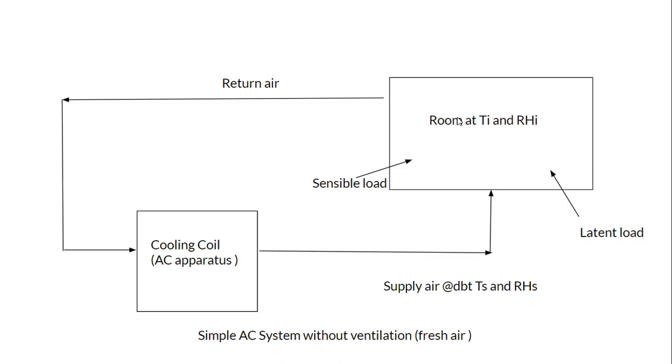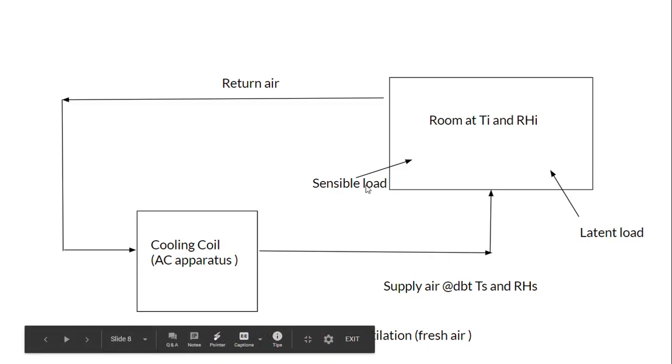In the last video we discussed the inside design conditions, that is, the temperature and humidity which are to be decided beforehand so that the occupants would feel comfortable. Similarly, we talked about outside design conditions, and we said that they are the temperatures and humidity one has to decide before the load calculations, and they would have an influence on ultimately the capacity of the cooling coil.